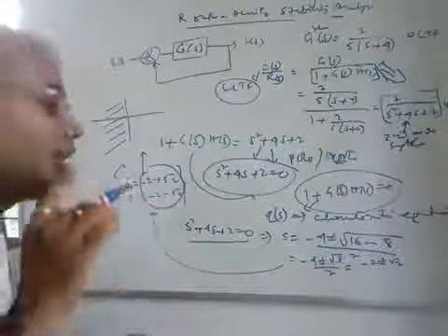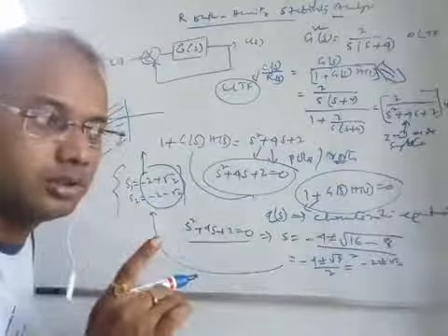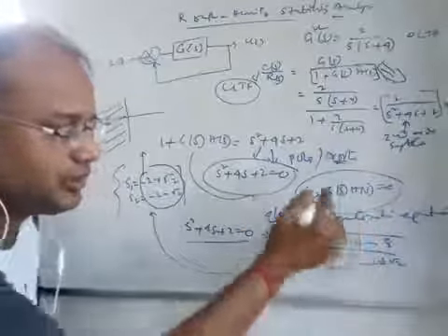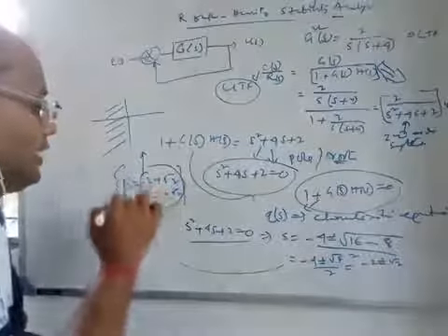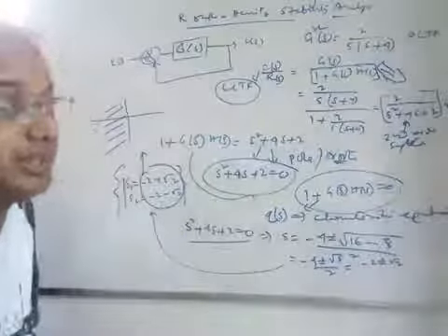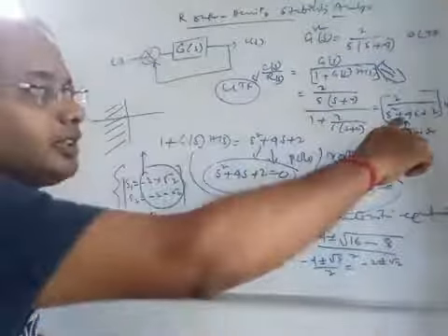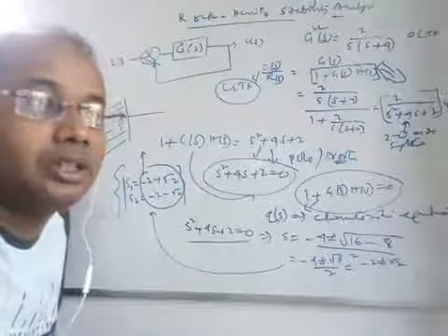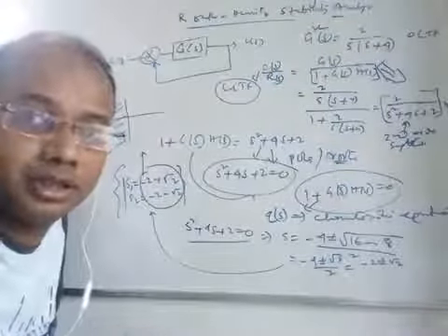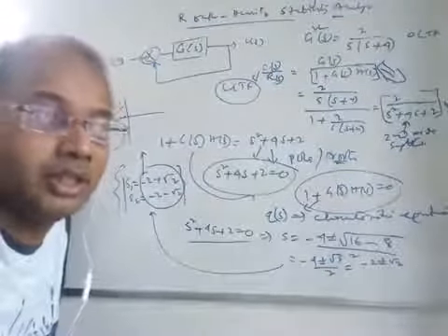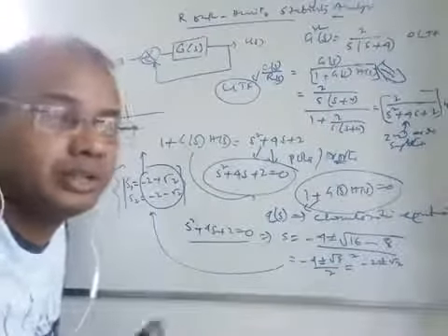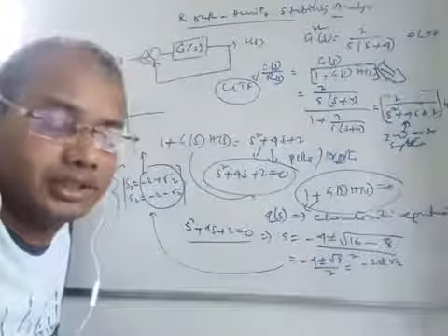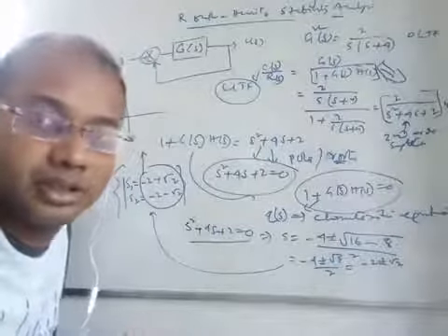That means once you can calculate the roots from the characteristic equation of any system given to you, if you can find the roots easily, then there is no problem. But the system may be such that the order may be 4, maybe 5, maybe 6, maybe 7, because during the block diagram reduction technique you have seen there are several blocks interconnected together. If, say for example, 3 systems are cascaded and each system has second order characteristics, then in total you get a 6th order system, right?